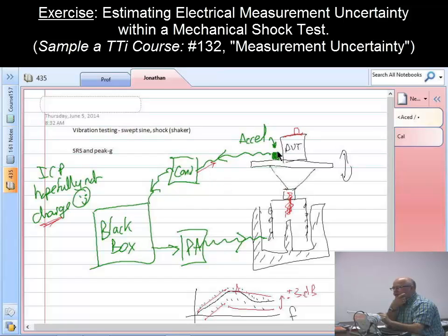to charge the electronics inside the accelerometer. Most of the signal conditioning actually happens with ICPs right down at that point. There's a little microcircuit built inside the accelerometers, and so this tends to be a very robust and noise-insensitive cable.